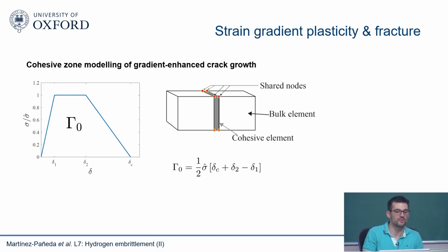We first started using cohesive zone models, before we looked into phase field. I don't know if you're familiar with cohesive zone models, but you can think of them as a glue, right? You have two pieces. If you know that your crack is going to grow in mode 1 along this line, you can put these cohesive elements here and think of a glue. You're gluing these two parts with some sort of traction separation law, some behavior that tells you how those two parts are going to separate from each other.